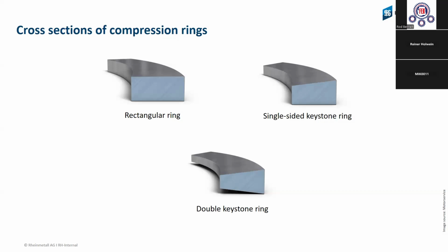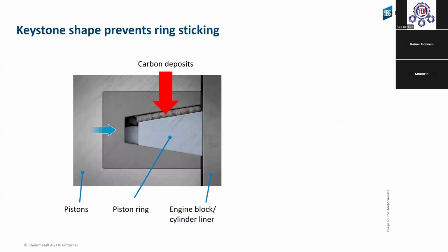When the piston goes up and down and has contact only left and right, we have wear only in these two places. This is why the piston ring must move completely, turning around in the ring groove every time, so that the wear will be the same at each position. And then we can seal.